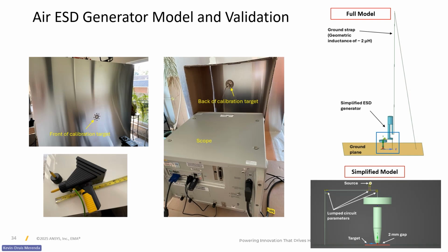So we started, Jennifer actually started, I think 3 years back, rented an ESD gun and had a 2 ohm target, and then a scope in the system. And then we had various ESD gun tips that were present, the contact ESD gun tip and the non-contact ESD gun tip. Our first model is on the right here, and you can see that it was very large.